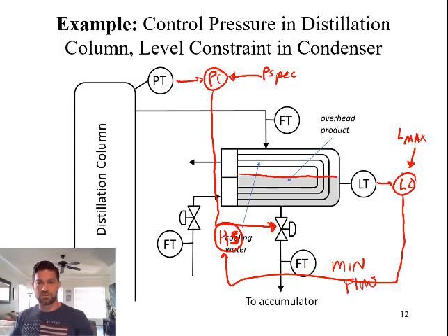Under normal operating conditions, this signal will be relatively low. As this starts to fill up all the way, that means the pressure in here is probably dropping. At some point, this flow will become too low, and at this point, the signal here will eventually drop down, become low, low, low.